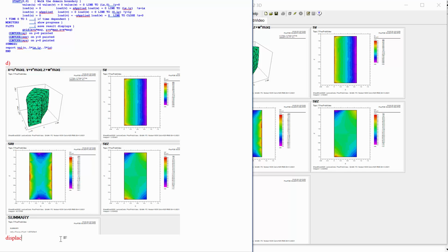So displacement is higher, 1.8 E minus 5, so like 18 mu meters, so 18 micrometers. You can turn on the option in Word to accept the math shortcuts outside of math areas, so you don't have to go Alt equals and type your equation. Mu, you can just get that outside of a math area if you put that option on. Anyway, so displacement is higher, 18 micrometers, and we've got a bending shape. It's not a pure shear shape anymore.